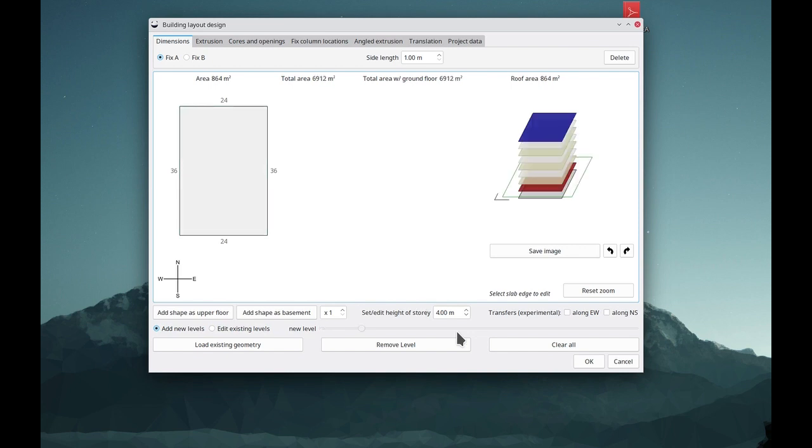Typically, just choosing the right decking can save perhaps 25% of the carbon and perhaps 15% of the cost, give or take. Of course, if you then adapt the layout a little bit, the gains can be as high as 50% of the carbon and 20% of the cost of a frame.